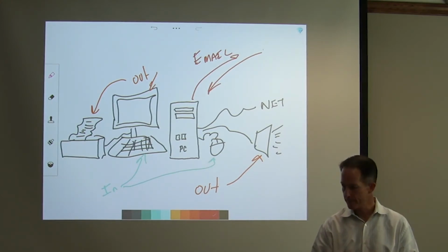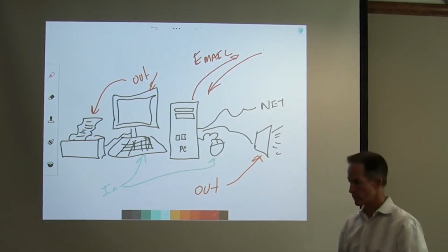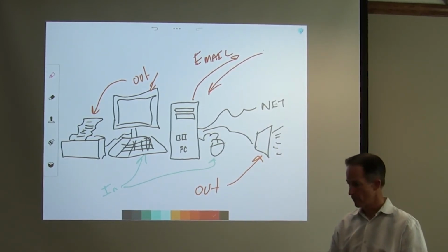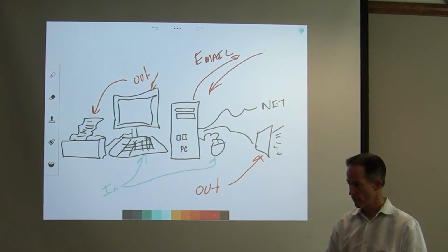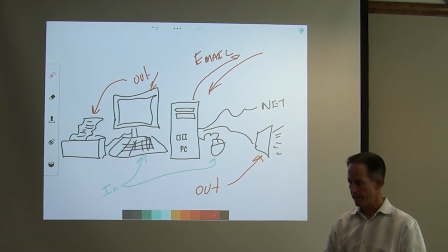One of the good things about the Delta is it has a lot of the controllers, say the computer's completely down. On that end, if you have power to it, it's got the manual dials on it. If you pull up the wiring diagram and know what it goes to, you can manual a chiller on, manual a pump on, and manual it with the controller itself, especially with the back plane, without having a computer to do it for you.